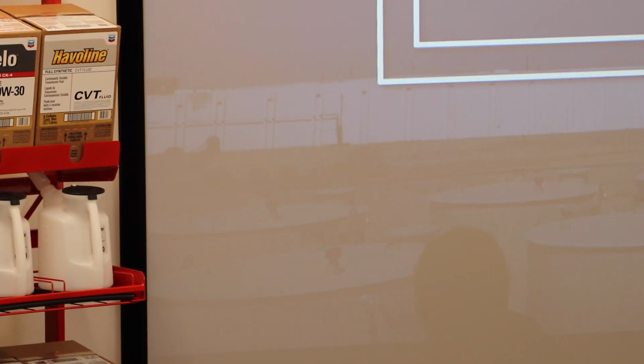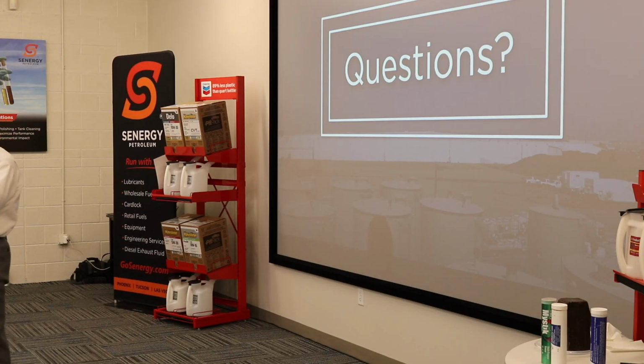So the question is with extreme impact and hydraulic hammers, the issue is the grease staying in there and getting slung out? Yeah. The best you can do for that situation is making sure you have something that has really good tackiness. That's about all between that and whatever mechanism is designed to seal it or keep it in place. But from the grease side of things, really tacky is probably the best you can do.